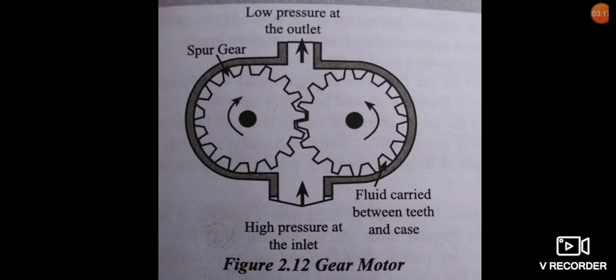Now, the rotary motors. The pneumatic motors convert compressed air to rotary motion. These motors can be utilized to provide a smooth source of power. They are not susceptible to overload damage and can be installed for long periods of time without any heat problems. They can be started and stopped very quickly, and with the pressure regulation and metering of flow can provide infinitely variable torque and speed.